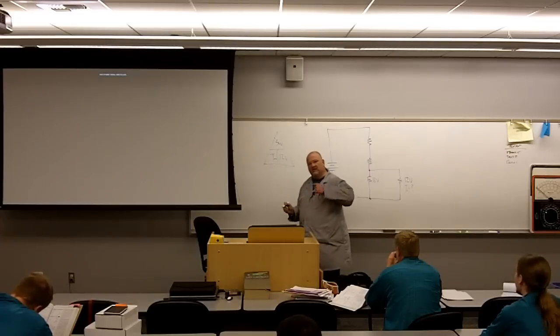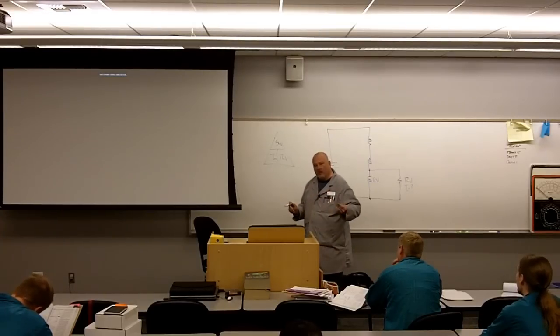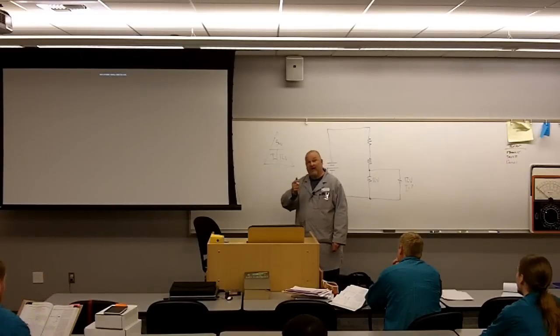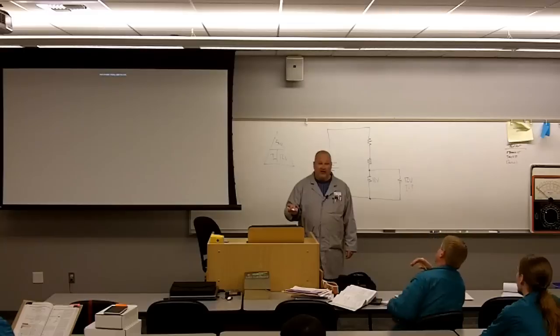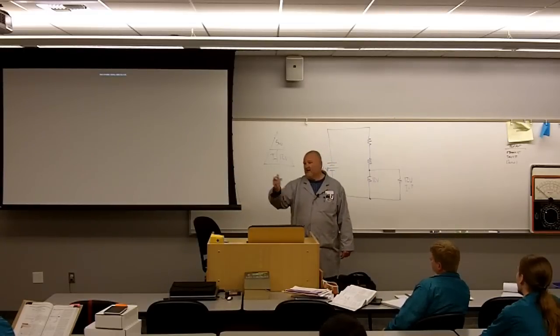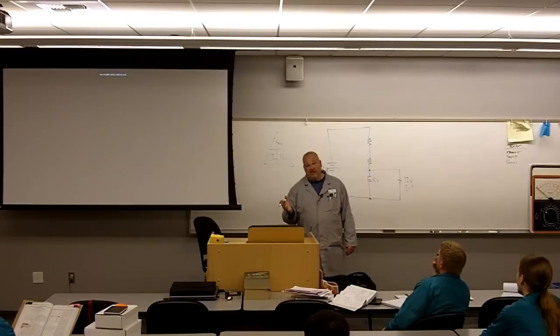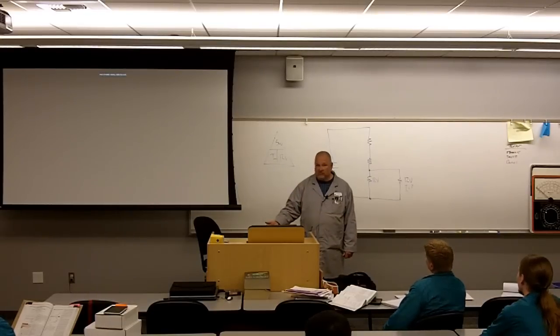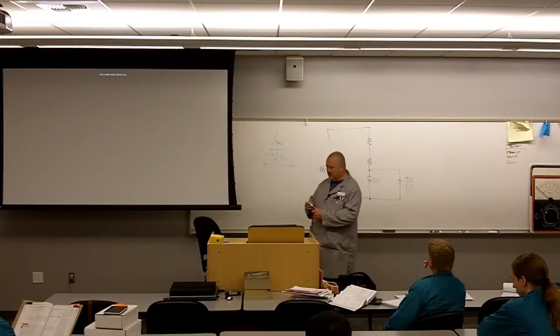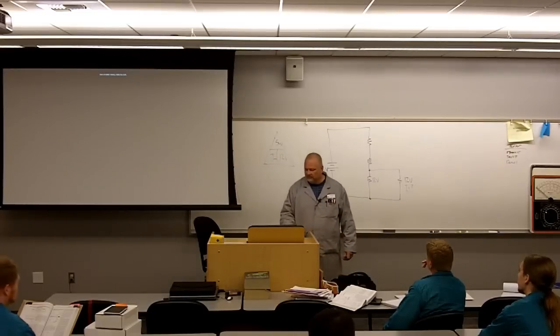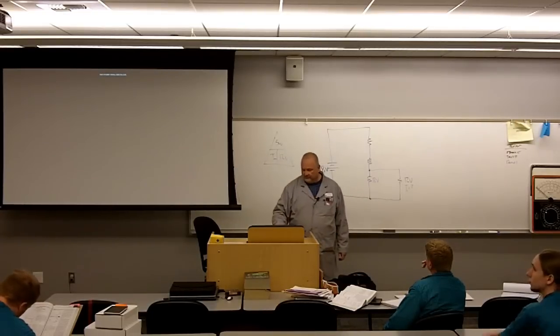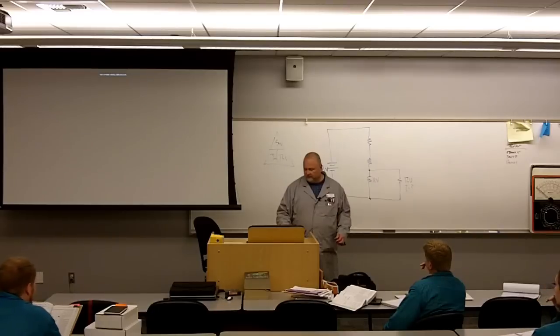So how much current is going to be required to power that radio when I key the microphone and broadcast out 5 watts? That's, by the way, the maximum you'll ever consume in a CB radio. If it's a 5 watt radio, the maximum you're ever going to consume is when you're transmitting. If you're just receiving, that doesn't consume much energy at all. It's when you key that mic and transmit that you start consuming the most power. So I'm thinking worst case scenario here.